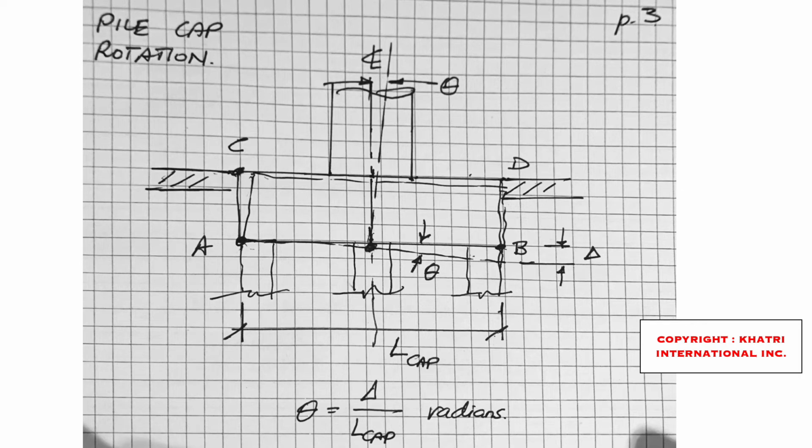If we are having this issue occurring in any building, it will demonstrate itself somewhere on a diagram like this, which can be measured. And so measurements to see if the building is deflecting are highly valuable, because that will tell us whether or not the building is sinking, if it's sinking by how much, and that will give us a prediction of what the stress increases is in the columns.